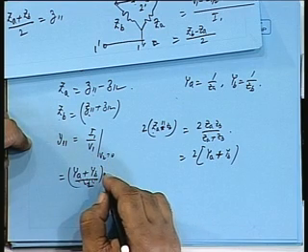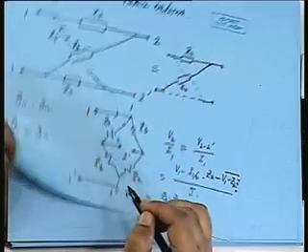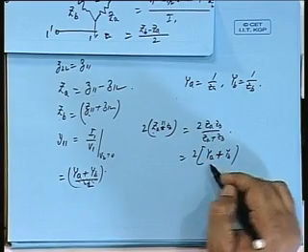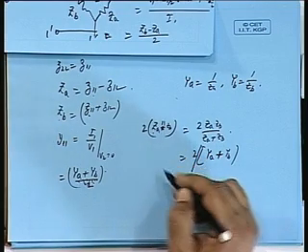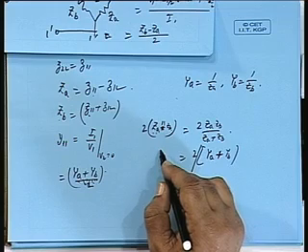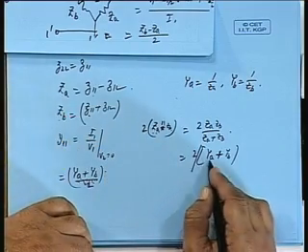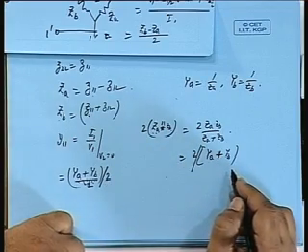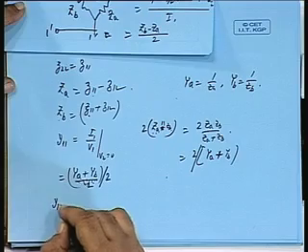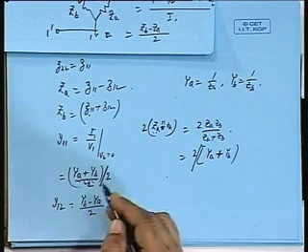So, Y11 is YA plus YB, into 2 or by 2? Into 2, sure. This is the parallel combination, so what is the inverse of that? So, this will be Y11 equals YA plus YB divided by 2. What will be Y12? Similarly, you will find Y12 will be YB minus YA divided by 2. You can verify for yourself.